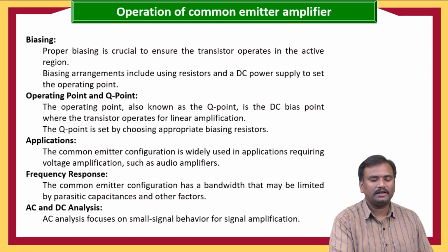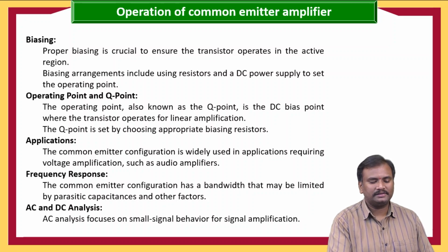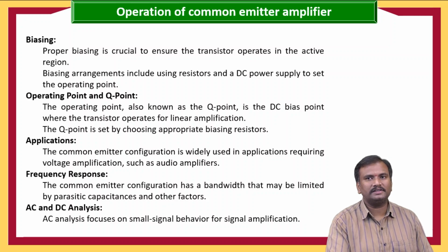The common emitter configuration is used in applications requiring voltage amplification, such as audio amplifiers. The frequency response in common emitter configuration has a bandwidth that may be limited by parasitic capacitances and other factors.